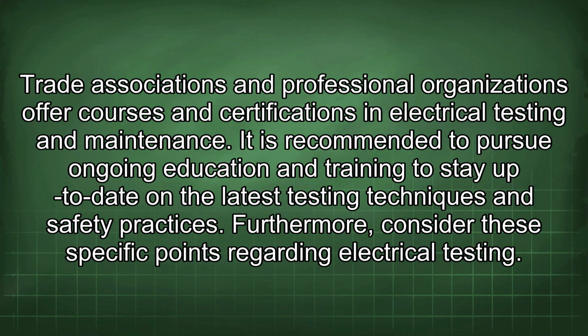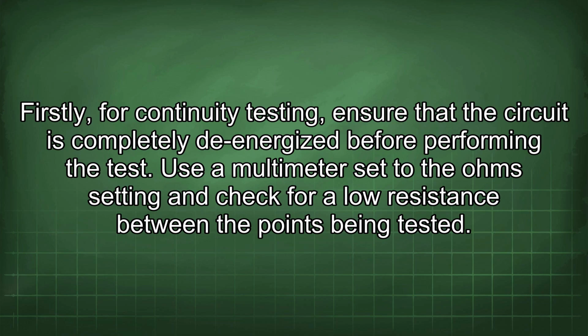It is recommended to pursue ongoing education and training to stay up to date on the latest testing techniques and safety practices. Furthermore, consider these specific points regarding electrical testing. Firstly, for continuity testing, ensure that the circuit is completely de-energized before performing the test. Use a multimeter set to the ohm setting and check for low resistance between the points being tested.